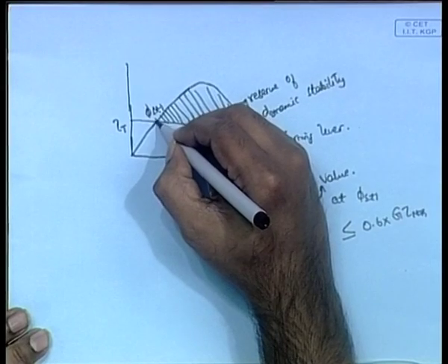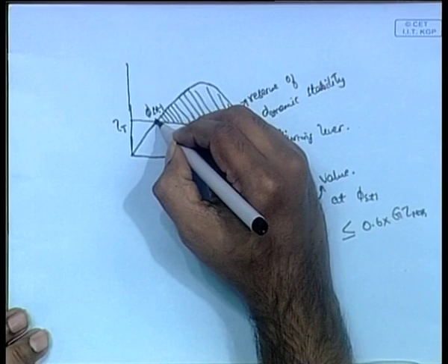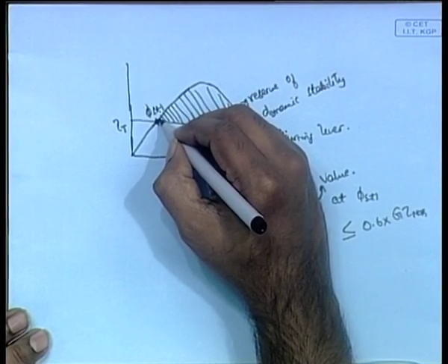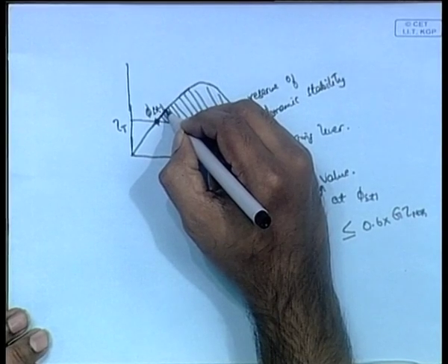So, we have phi st1 and phi st2, both known as angles of statical stability, but there is a slight difference between the two. If you look at the first, phi st1, in this figure, you will see that if the ship heels more than this phi st1, let us suppose the ship has heeled here, what do you see?